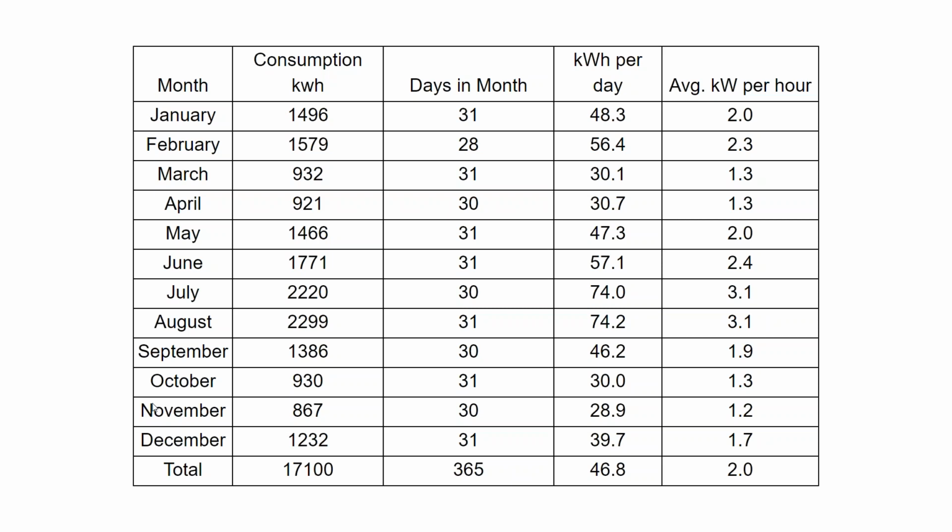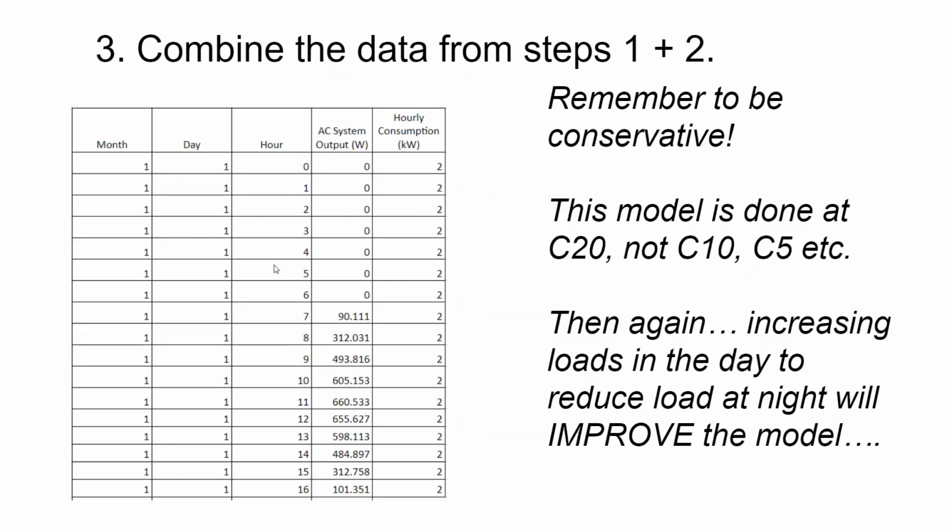Okay, so we have a few more questions about, do you want to limit the battery draw to 50%, and what does C20 mean? We're going to get to those technical discussions when we get into the battery discussion. But in general, the draw from the battery bank is going to be less than 50% on these kinds of off-grid systems.